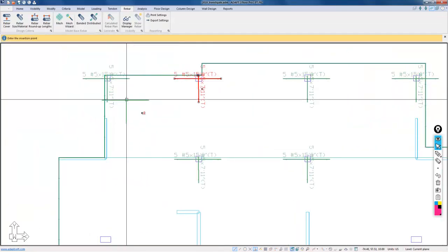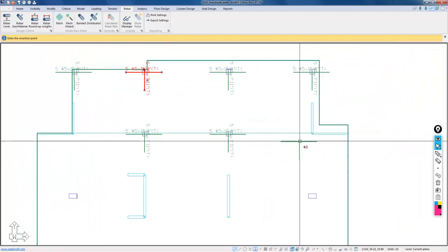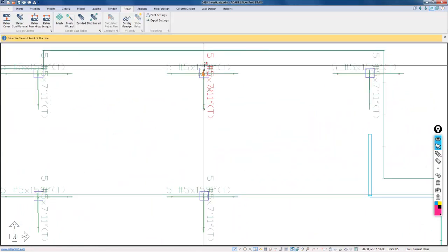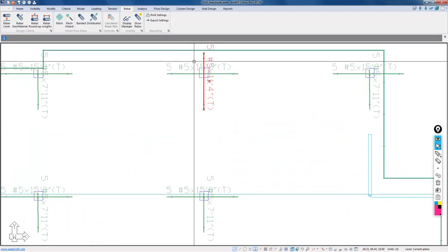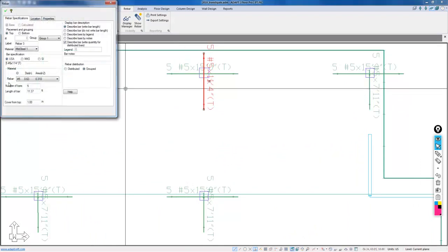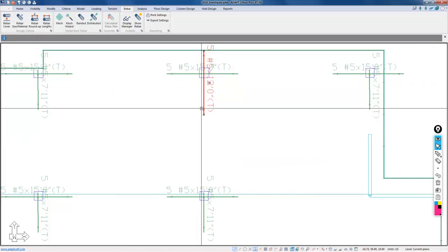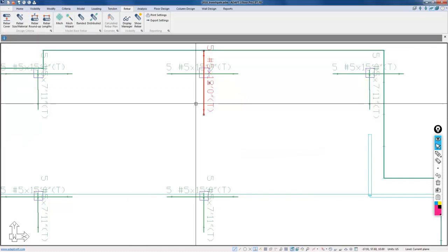And then I'm actually going to adjust their lengths. I'll come back and do the walls. So this bar, I'm just going to take this point and just drag it. If I wanted to manipulate the length, I could also just come here and say, well, I want to make that bar 13 feet, and then I could reposition the bar by moving it.